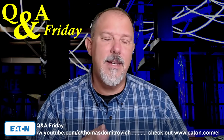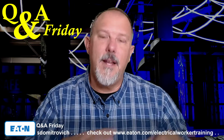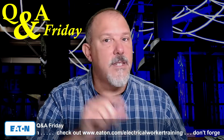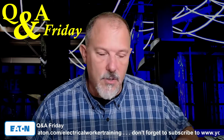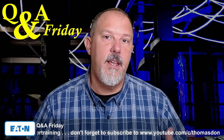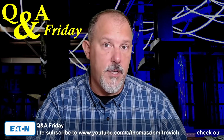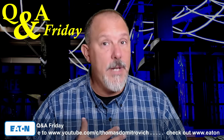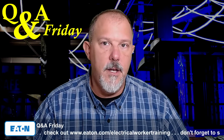Now, and I say that, hold on. I do say there's not a lot of areas. There are some instances, minor instances, where they have the 125%. But if you look at 210 for feeders, we do say that you have an exception if it's 100% rated. And since medium voltage equipment is 100% rated, you can leverage the exception. So what I think you're going to see, at least what we did in 231, was we moved the requirements over just as they are in branch circuits. And you'll look at it and say, well, that is the exact same language that's over in 210.19.